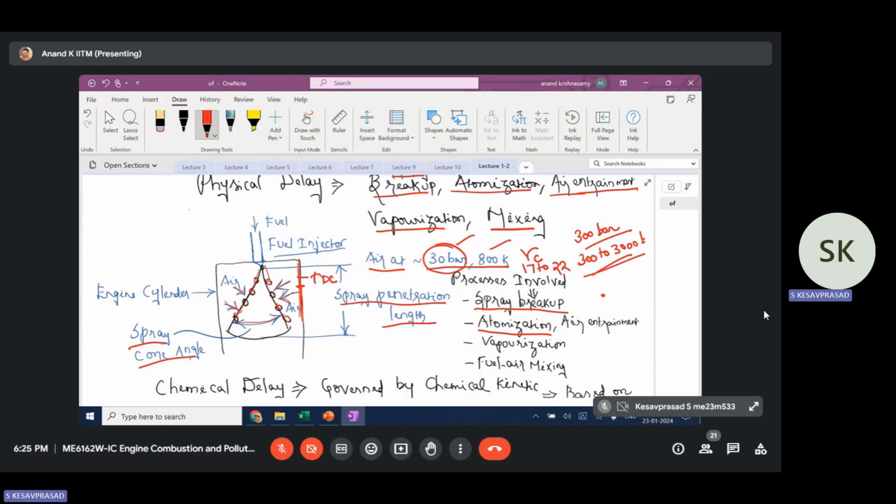something else has to happen, right? So this is liquid phase fuel. Before mixing, something has to happen. Proper atomization. Atomization, sir. Phase change. Break of molecules, sir. No, this is liquid phase. Combustion is gas phase. So what should happen? Phase change. So phase change, atomization and vaporization.